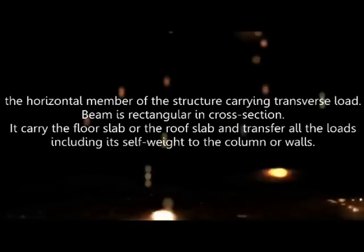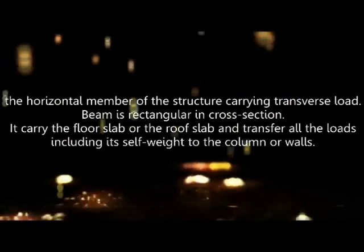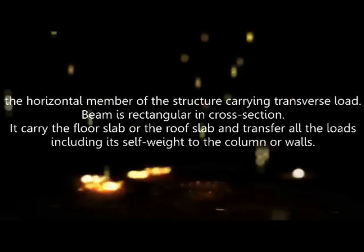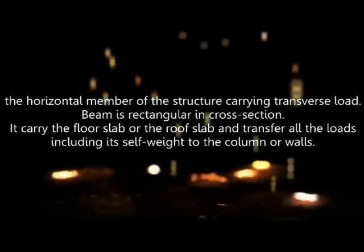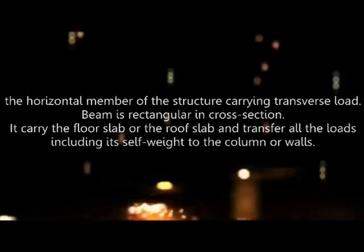The beam is the horizontal member of the structure carrying transverse load. Beam is rectangular in cross-section. It carries the floor slab or the roof slab and transfers all the loads, including its self-weight, to the columns or walls.